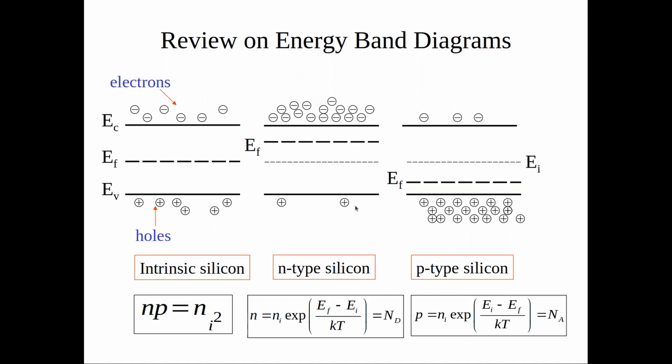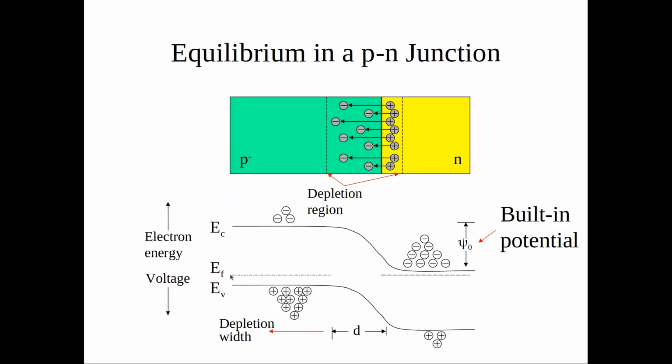If you put the Fermi levels aligned, which is typically what you would need to do, it's one Fermi level. Then what moves around is the distance from the Fermi level of the conduction band and the valence band. So in an energy band diagram, this would be the proper way of drawing things: to keep the Fermi level always aligned and then put all the other levels relative to the distance. And this is what happens if you put this p-n junction together. So this is going back to this diode.